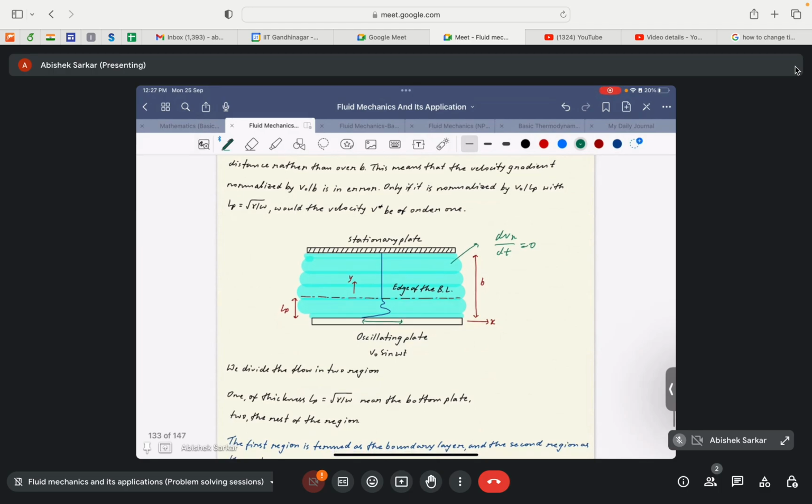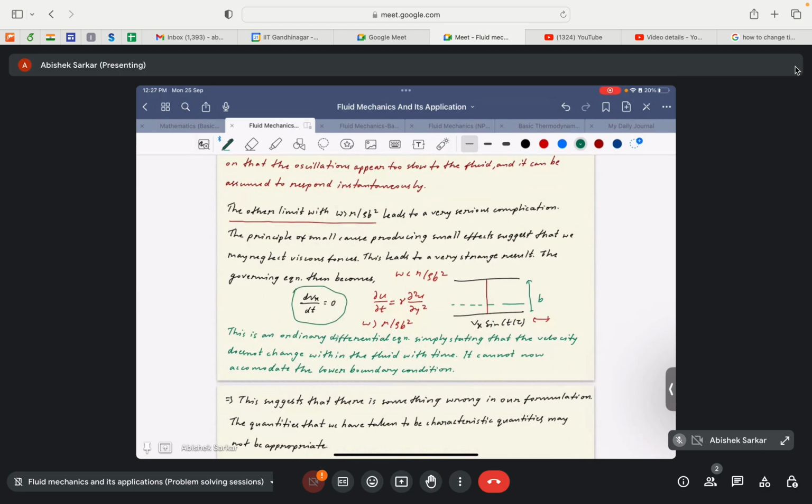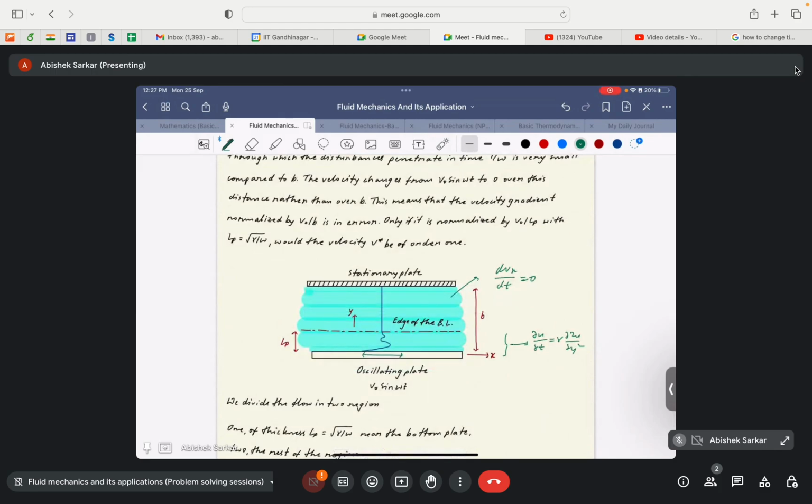But within this region, also known as the boundary layer, this equation is not valid, and actually this equation itself has to be solved with different scaling terms. Okay, so that's the essence of the problem, right? The scaling that we chose, or the governing equation that we got after scaling for this case, is correct, but is valid only for the outer region, the region beyond the boundary layer, right? So within the boundary layer, again we need to take the same governing equation that we started with, scale the governing equations with different scaling terms, and then try to see which terms can be cancelled out or considered.